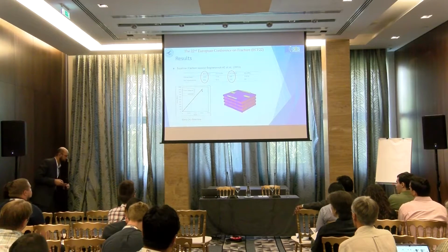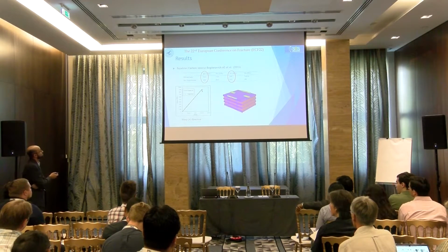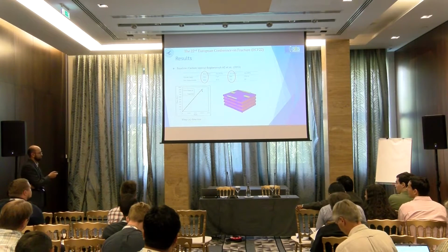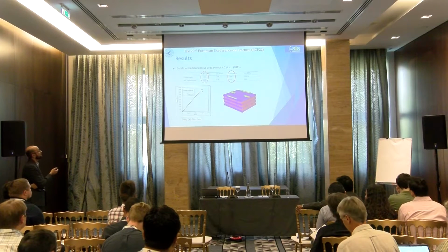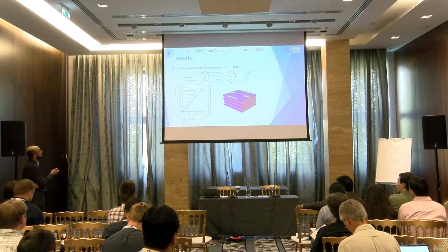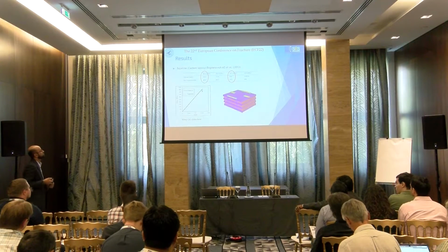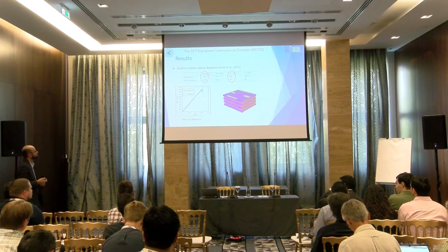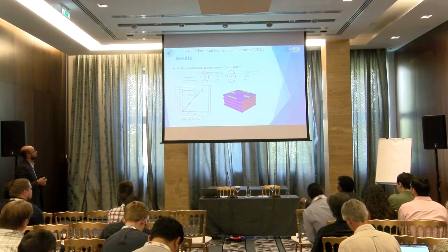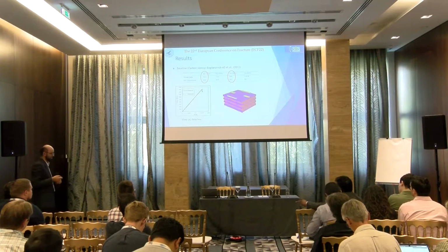Now coming to the results, first the baseline carbon epoxy, which has been experimentally analyzed by Bogdanovich. In direction 1, the warp direction, the main load carrying fibers, as we can see in the stress plot, are the warp fibers, and the results here are excellently matched with the experimental data.